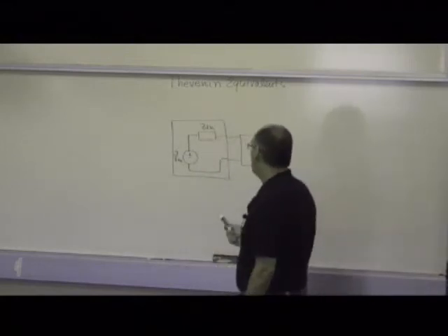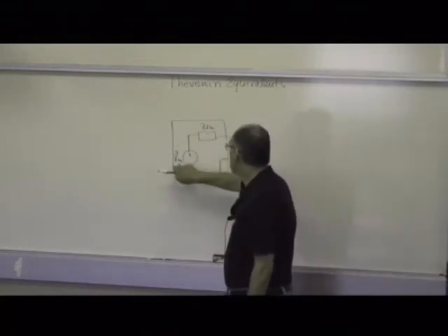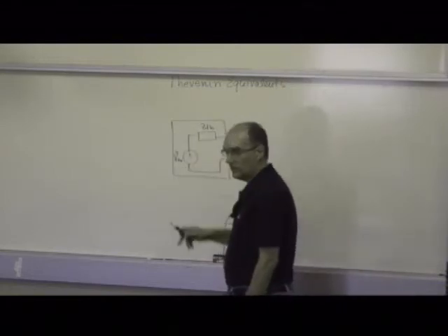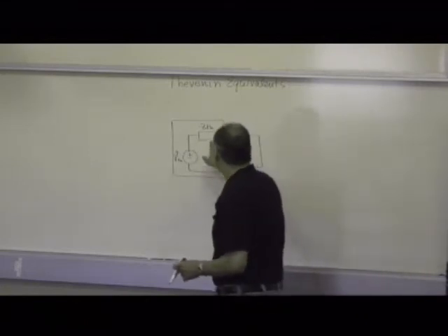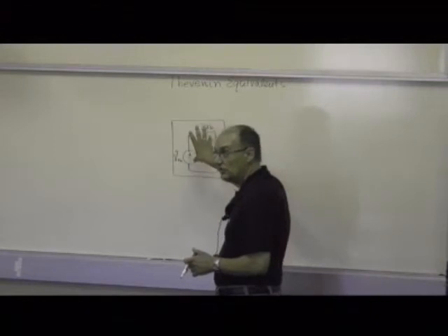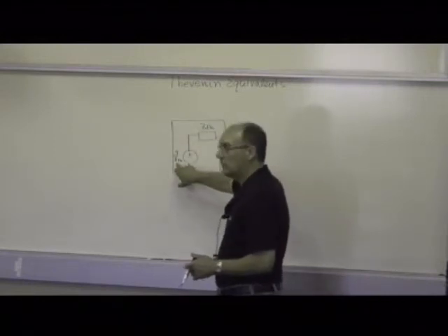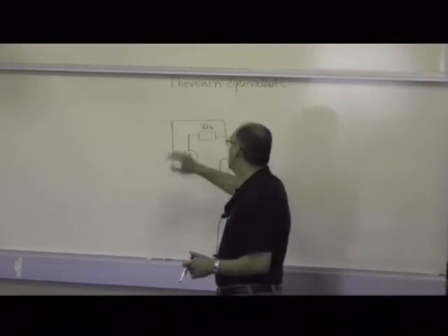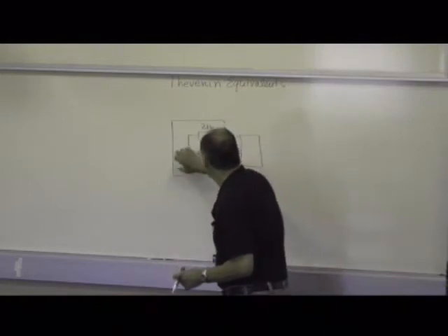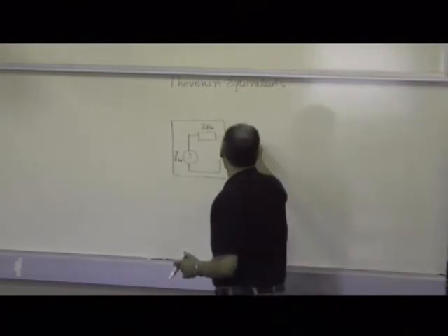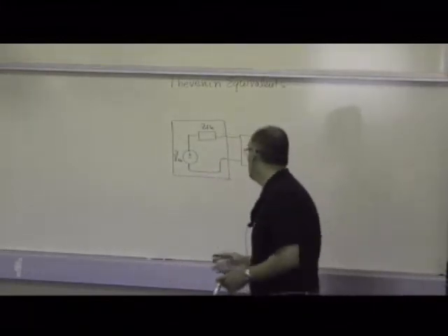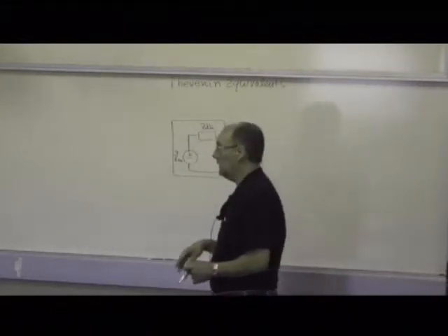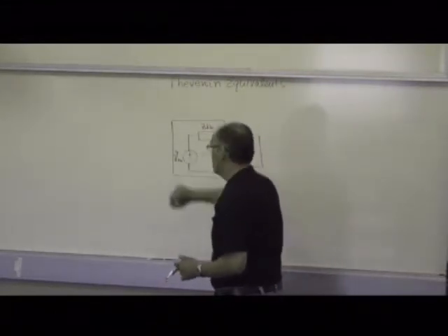Now, I will point this out. Thevenin equivalents are always kept in complex form because a Thevenin equivalent is generally never the end of your problem. You usually have something more to do. It's a simplification. So you don't want to convert V Thevenin into a sinusoidal form right now. That's something that you don't care about. You will keep both V Thevenin and Z Thevenin as complex numbers. When you're done with all your calculations, then you will convert whatever currents and voltages you're interested in into sinusoids, but not in the Thevenin stage.